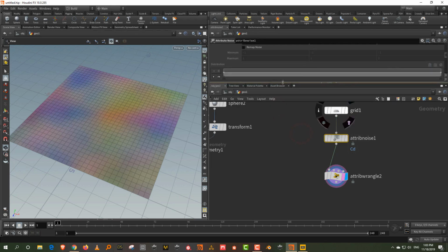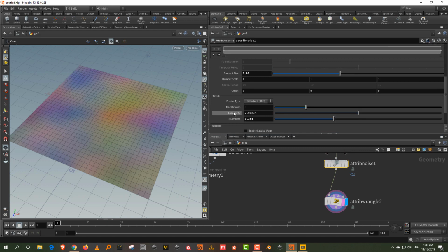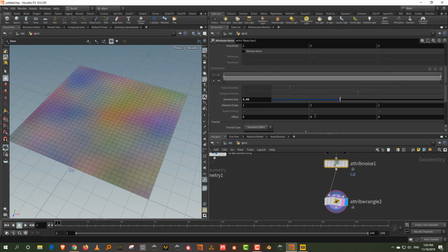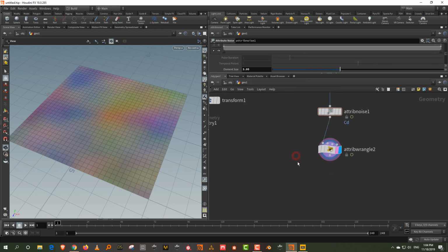And let's also do one thing. Let's take the noise and we will animate this. The simplest way to animate is to take the offset value and just animate it. So I'll come into the y offset and put in @Time. So you should have an animated noise map. Okay, pretty simple. Now let's take a poly extrude.